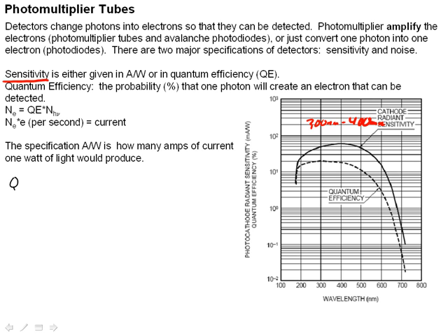The quantum efficiency is defined to be the number of electrons that come off the photocathode, before they're amplified, as a function of the number of photons that hit it. And let's take, for our case, the quantum efficiency at 400 nanometers, down in the blue-violet region of the spectrum.